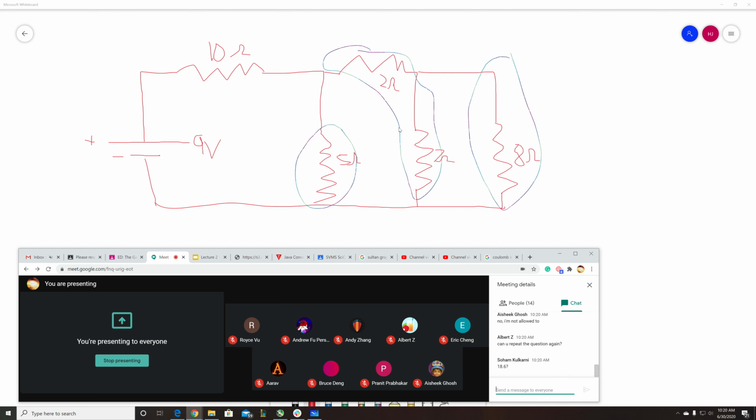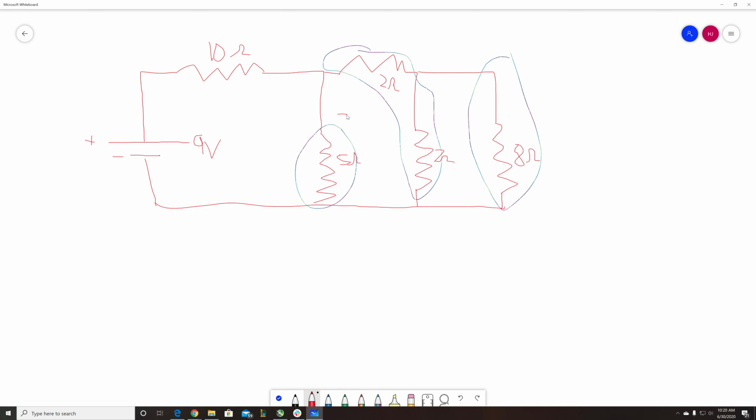Actually, I did not even ask a question. Okay, I want to know the current. Say this is I1. I want to know I1 here. I want to know the current I2 here. I'm giving you the direction of the current. Another thing to understand is that if the direction of the current is not what the question says it is, the current is probably negative.